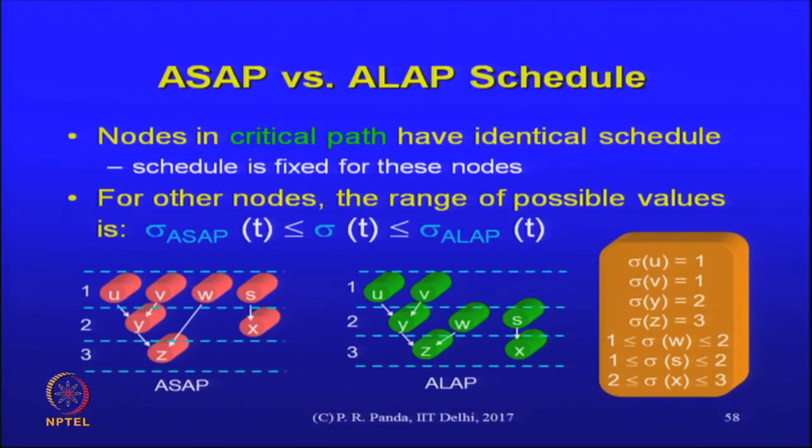The information that we have here is that if you make the ALAP deadline the same as the ASAP critical path in terms of number of cycles, then the scheduling ranges that you come up with, scheduling range being defined as all the cycles, all the states between the ASAP and the ALAP where that particular operation can fit, give us an idea about the flexibility that the scheduler has with respect to that operation.